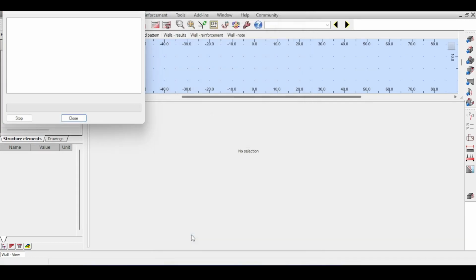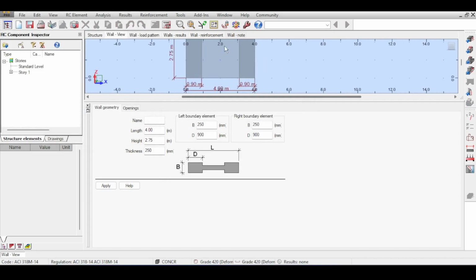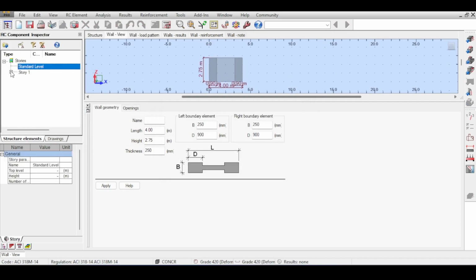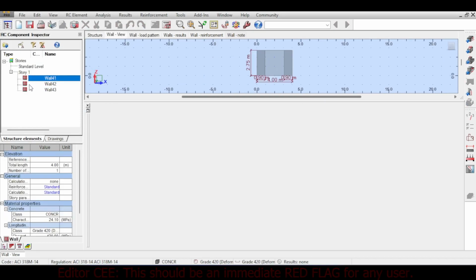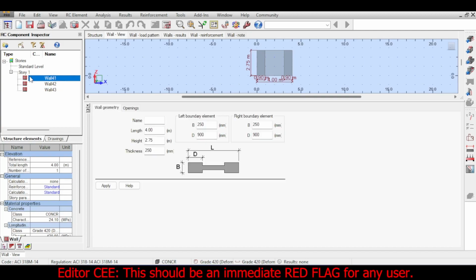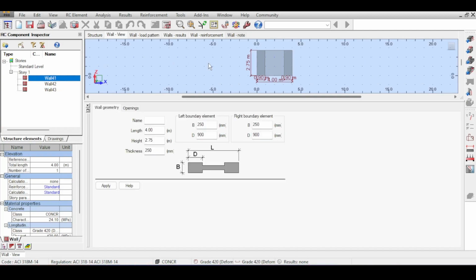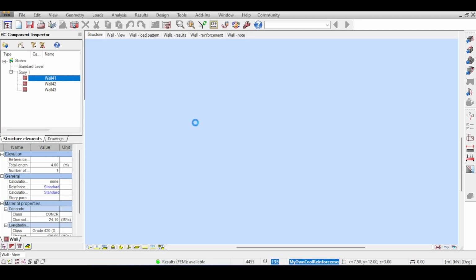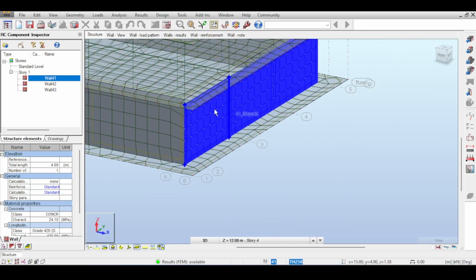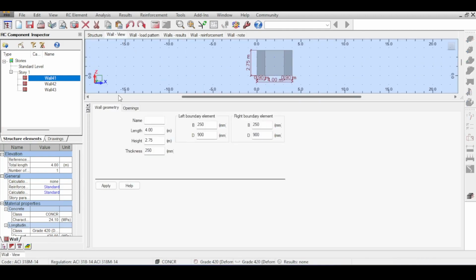If you click on OK now, it doesn't import all the 3 walls as one wall. Rather, it imports each wall separately, which is kind of odd because it's one unit and you would have steel bars extending from one wall to the other. I mean, look, you would have steel bars just extending the entire length. But Robot doesn't understand this. Robot just takes it as a wall. Now, why should you not use the wall?